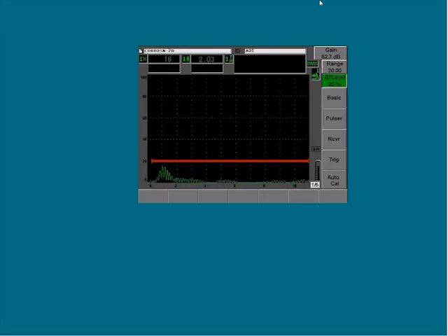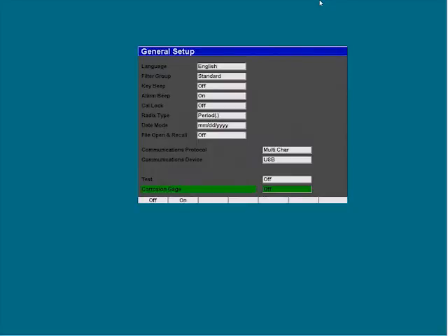So it's absolutely possible to use a flaw detector as a corrosion gauge and get fairly repeatable and reproducible and accurate results. However, the amount of setup and the amount of continued vigilance by the operator is fairly high for a standard operating mode. If instead I switch the instrument over, so I'll go to my instrument setup general menu, because I'm going to change the mode of the instrument from flaw detector to corrosion gauge, so I'll turn this on. Now you'll get an impression of exactly how powerful this can be and how simple.